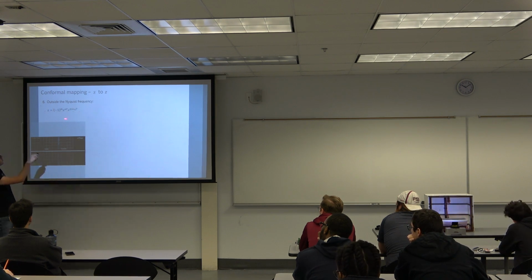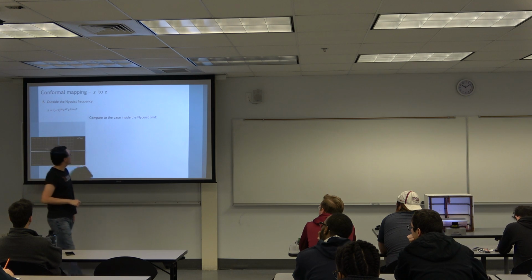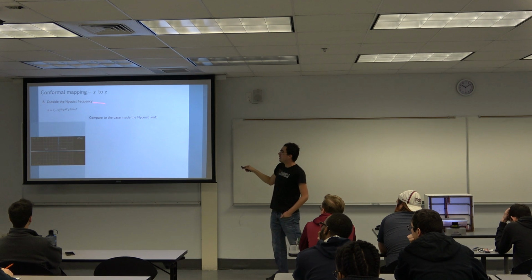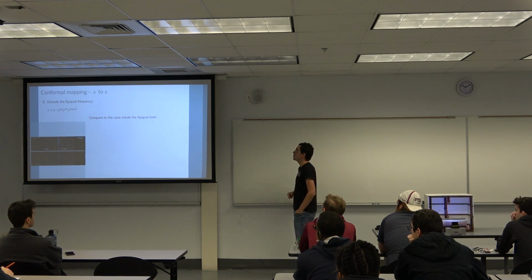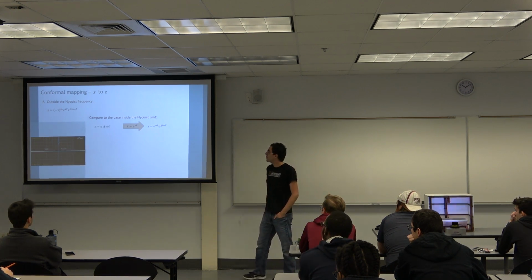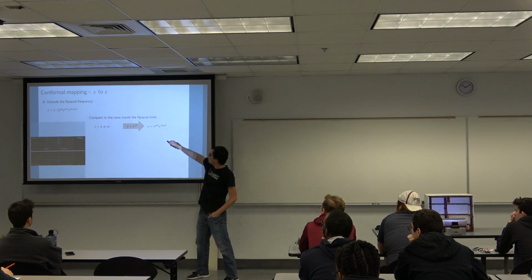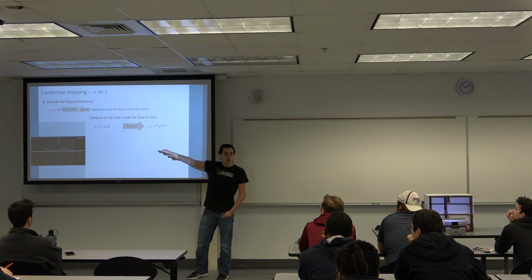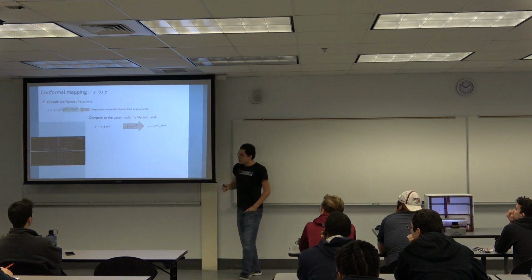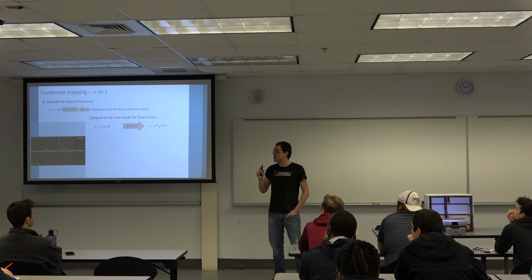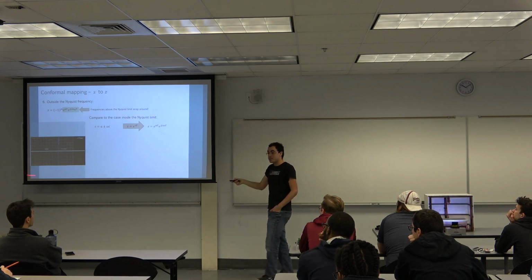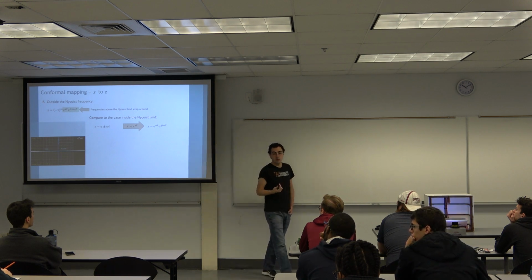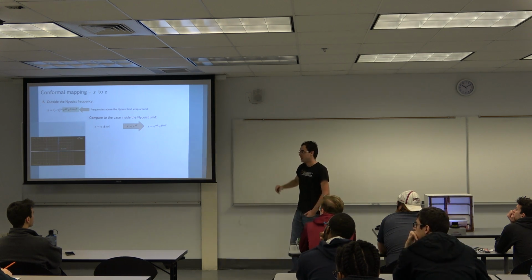So I'm going to copy that expression over here, and I'm going to compare this with the cases where we were inside the Nyquist limit, where it looks exactly the same. And if you compare the expressions, they're exactly the same, except for the minus 1 factor. So this means that the frequencies above the Nyquist limit are actually landing exactly where the frequencies inside the Nyquist limit land. So the Z transform folds on itself.